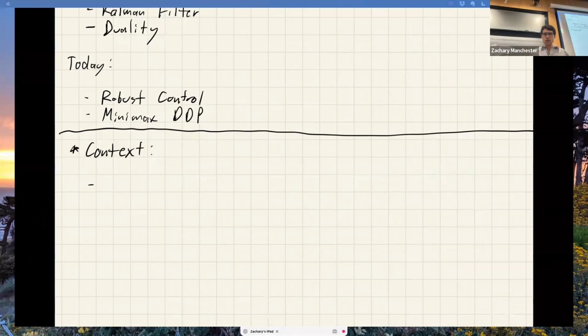The thing that's important to realize is that it is very common in practice, and you are frequently tempted, to wrap modeling error into these noise terms. You can say, oh, I have process noise. Whatever is wrong in my dynamics model, I'm just going to inflate the noise and treat it as noise. But that can be a bad thing in a lot of situations.